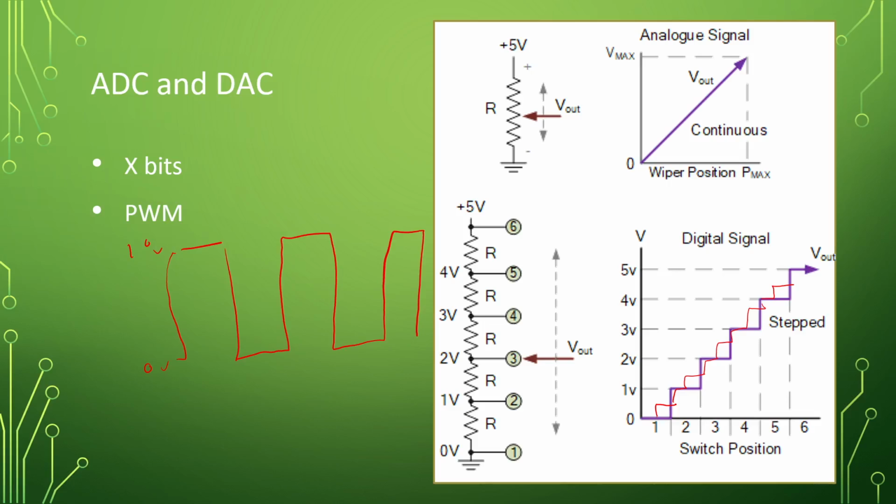If you really wanted to expand on that, you would put maybe some inductors and some capacitors in there to help resist the change, especially inductors. They don't like to change. Once current's flowing, they want to keep the current flowing. So by pulsing an inductor, it will help average that out for you. I wish I had an inductor up here so I could show you: this is without an inductor, and you see the pulses.